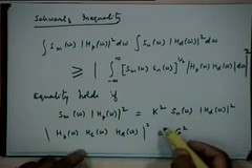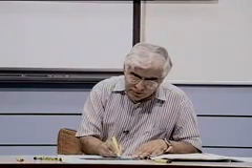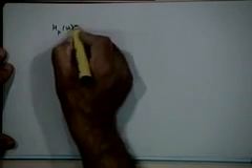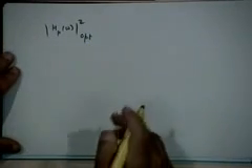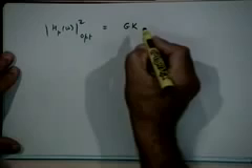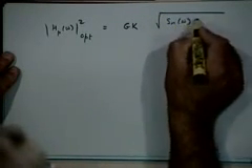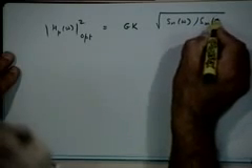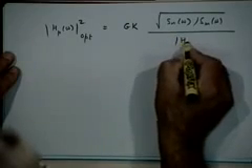You can do that using these two equations, and it is very easy to check that your optimum value of Hp(ω), the pre-emphasis filter, should have a transfer function equal to G by k times the square root of Sn(ω) upon Sm(ω), upon mod of Hc(ω).